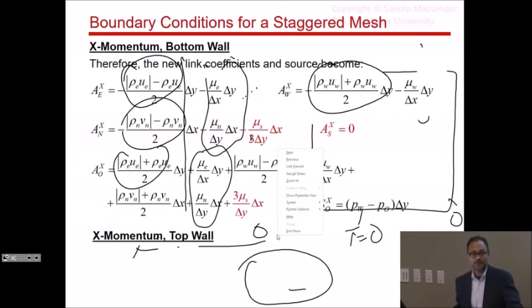All right? Now, one thing you could also check is you could say, well, I know what the solution is going to be in the pure diffusion case. How would I know if with advection it's working correctly or not? Well, what you can do is you can set your U lid to be a very, very small value so that the solution is still diffusion dominated and it would still look like the first iteration solution. Okay? So, I mean, those are all different things one could do to make sure that you're on the right path in developing your Navier-Stokes solver.